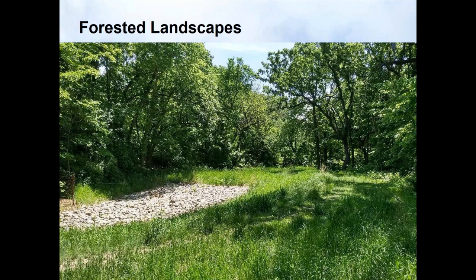So we took about 4 acres of residential runoff and brought it to this area, treated it upstream, and then we infiltrate it here before it goes over a level spreader over the berm in the middle. Since we've had this installed, I don't think we've ever seen it actually go over the level spreader.